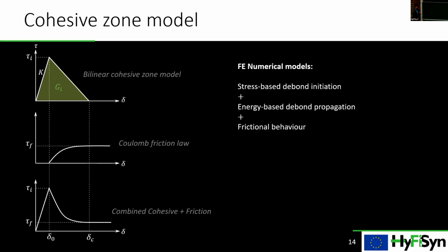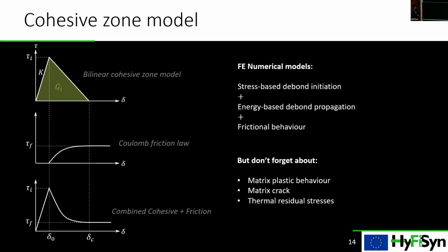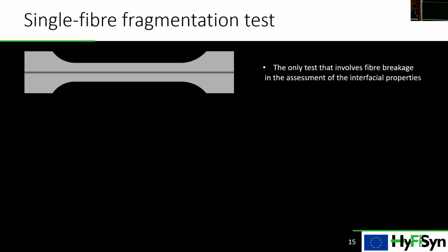But if you are going to use this, don't forget to take care of these other things that are happening in interfacial failure, which are that the matrix plastic behavior should be included. And you could also consider the matrix crack, and also the thermal residual stresses should be taken care of.